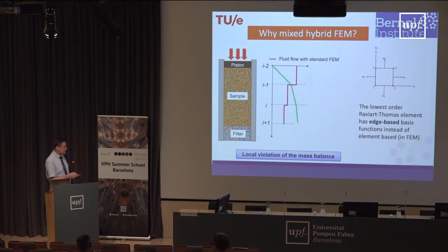Just a very simple experiment. Many of you who have been working on cartilage will know the consolidation experiment: consolidation, confined compression. We have a sample of cartilage or whatever lying on a filter. We put a piston on it and we push out water. And as we push out water, we get a settling of the cartilage because water is pushed into the filter.